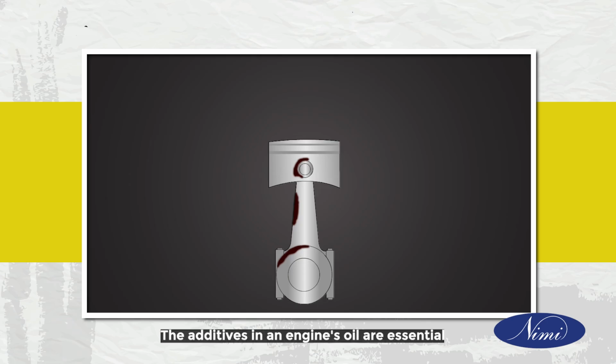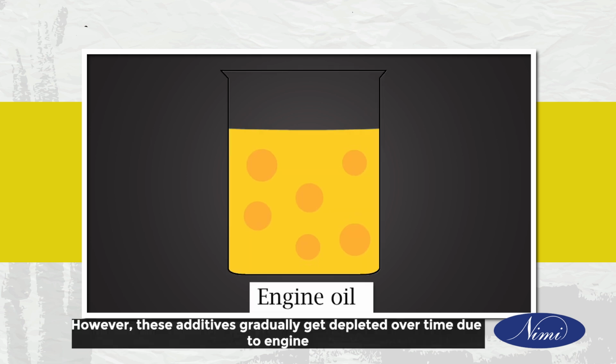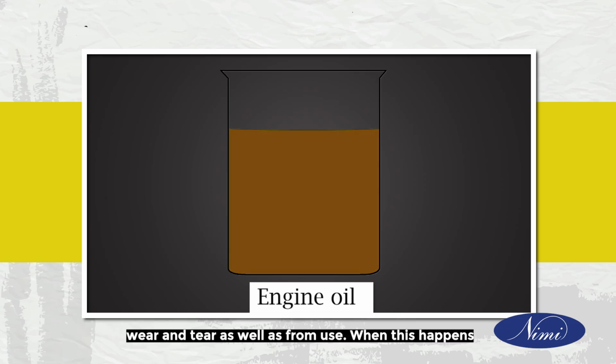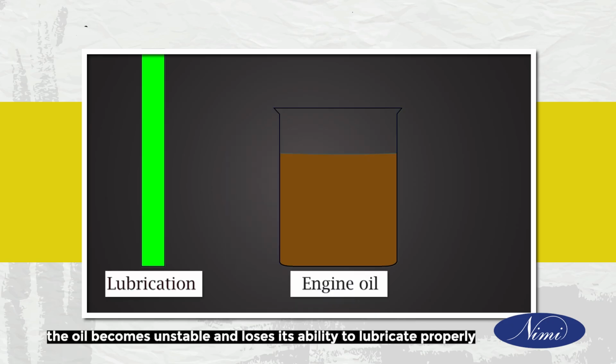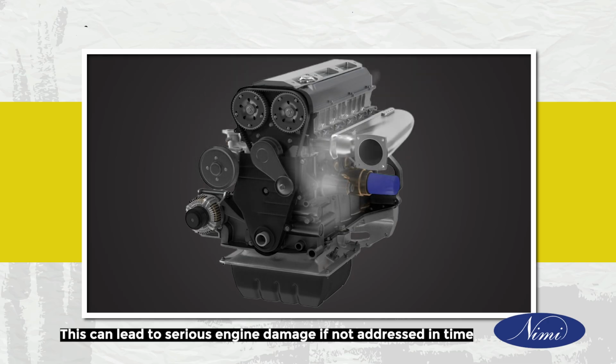The additives in an engine's oil are essential for keeping it clean and stable over time. However, these additives gradually get depleted due to engine wear and tear as well as from use. When this happens, the oil becomes unstable and loses its ability to lubricate properly. This can lead to serious engine damage if not addressed in time.